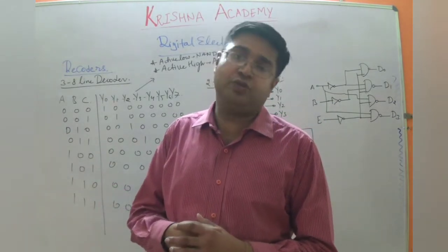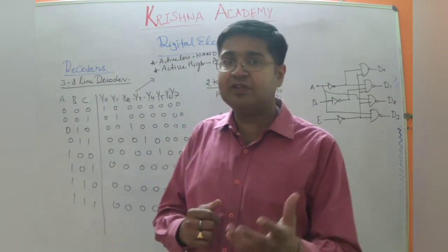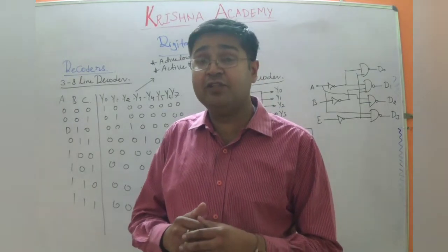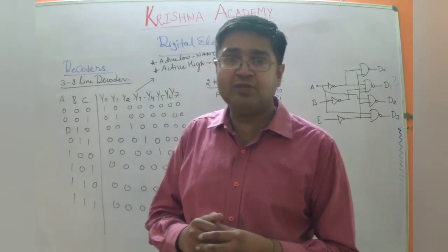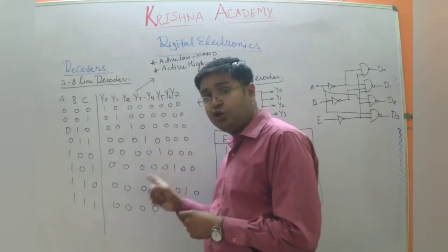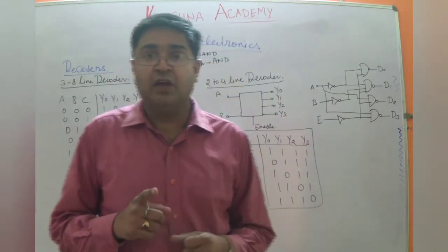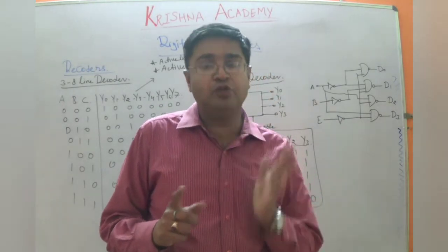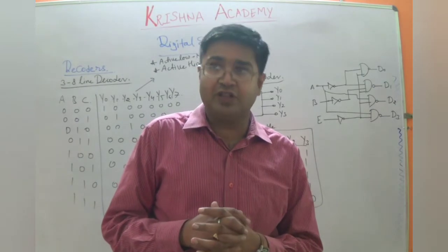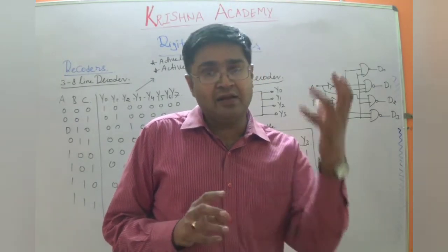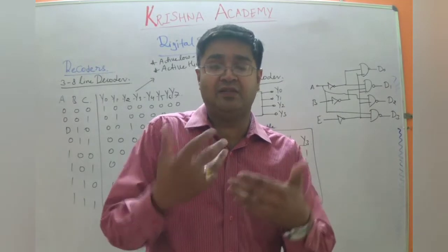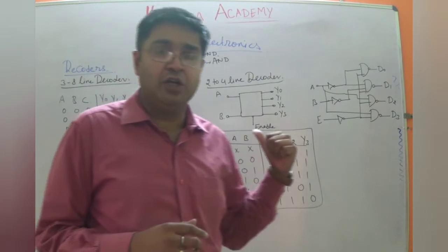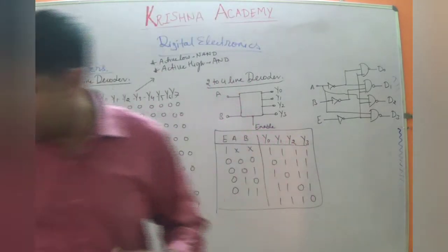By using AND gates or NAND gates, you can make this decoder circuit quite useful. Now, is there a possibility that we can use this circuit for a full subtractor? Yes, a 3 to 8 line decoder can be used as a full adder, as a full adder circuit. And if we want to implement a bigger decoder other than this one, then there is a possibility we can do it. So we'll talk about this.